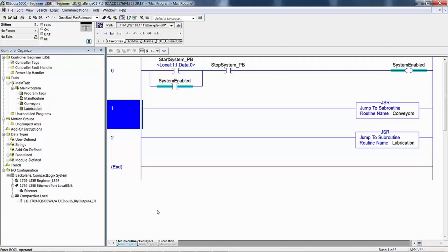We need 1 at the entrance of all 3 conveyors, positioned to sense the leading edge of a part arriving and trailing edge leaving. We can use timers and counters for the remaining sense, so to speak. We would know how long the conveyors are and the surface speed of each conveyor belt, thereby being able to predict exactly where on the belt an object is. Now we're not going to go to that length in this particular challenge, but you could do that.